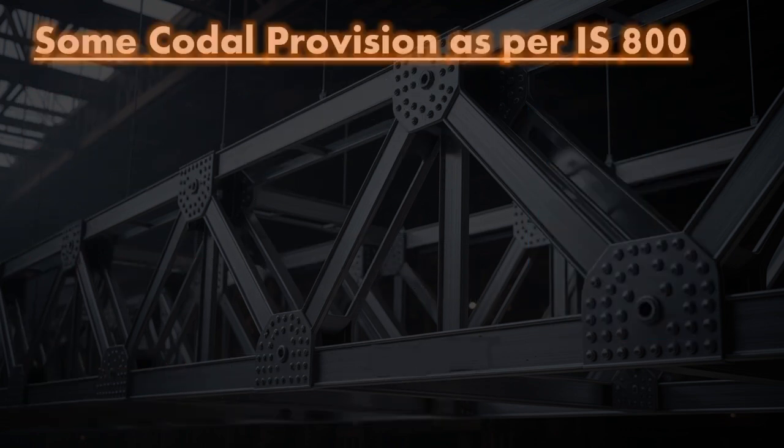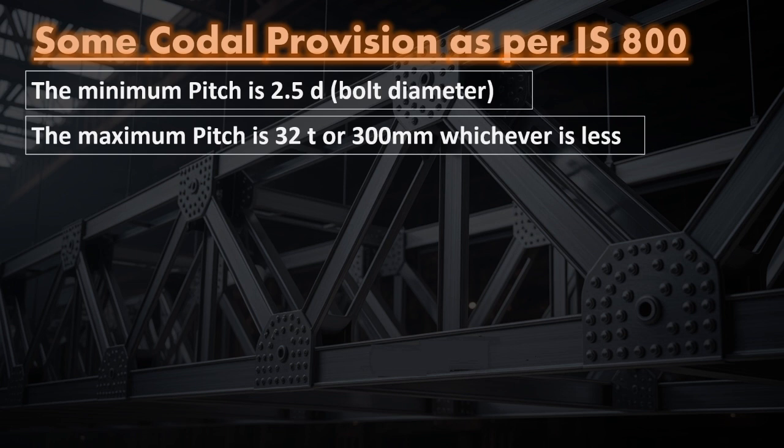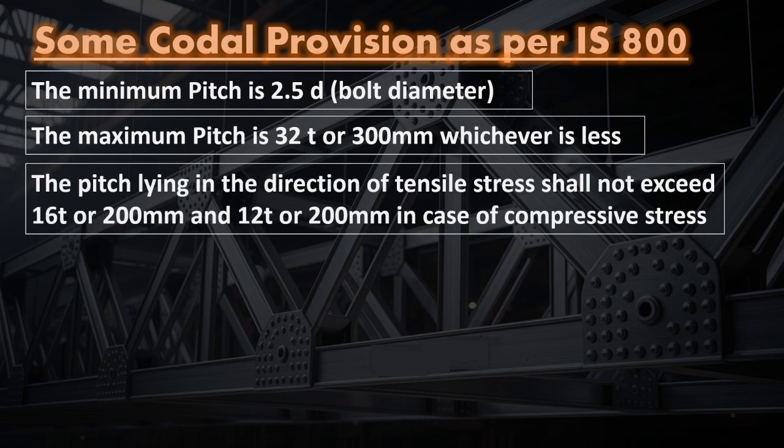Some codal provisions as per IS 800. The minimum pitch is 2.5 D, where D is the bolt diameter. The maximum pitch is 32 T or 300 millimeters, whichever is less. The pitch lying in the direction of tensile stress shall not exceed 16 T or 200 millimeters, and 12 T or 200 millimeters in case of compressive stress.